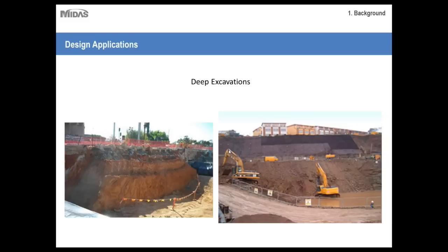And then naturally, deep excavations. Whenever excavations for foundations are created, slopes are a natural part of creating these foundations. Until these foundations are built, the stability of these slopes needs to be checked and designed for. Oftentimes there are tiebacks or soil nails that are installed into these slopes to support them.